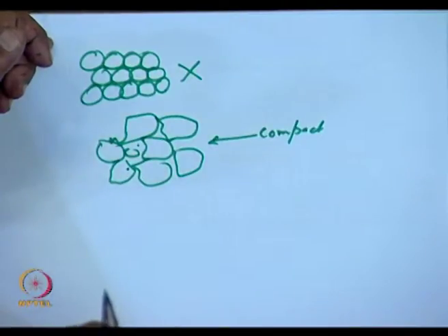Normally, if I have taken a ceramic powder and compacted it in a die, even under the best of conditions, I do not expect more than 60% packing. That is, 40% of the space will be pores.